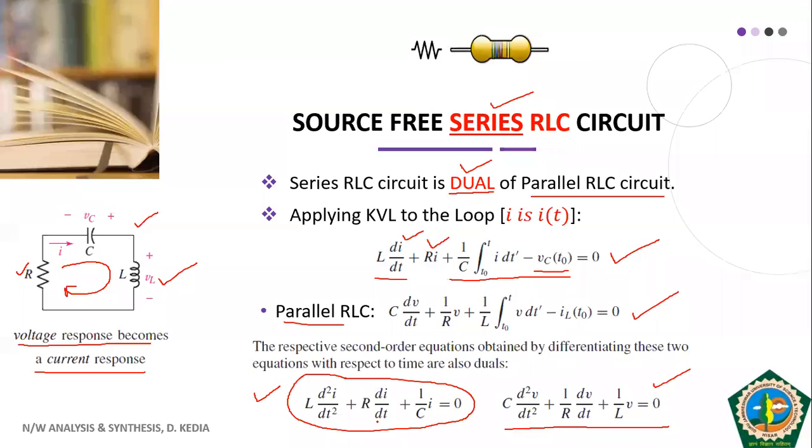So students, you can compare this equation with the equivalent equation in case of your parallel RLC circuit. You can see that they are pretty much similar. Both have the same kind of differential equation. The only difference is the constants or the coefficients of this equation. So that means the same kind of analysis that we have developed for parallel RLC circuit will apply to series RLC circuit also.